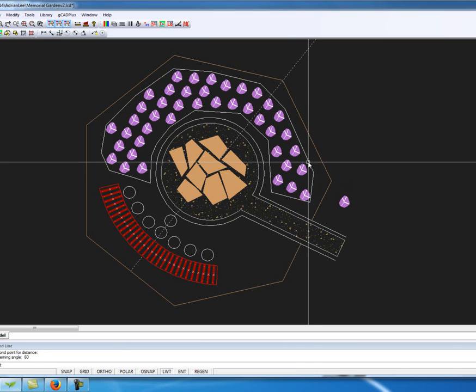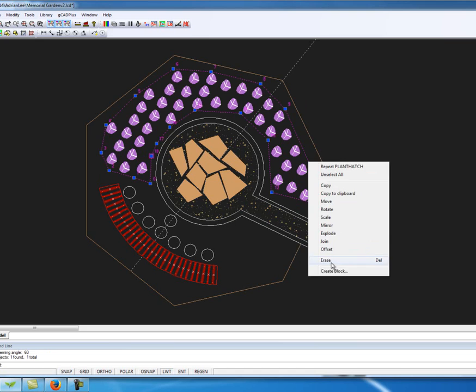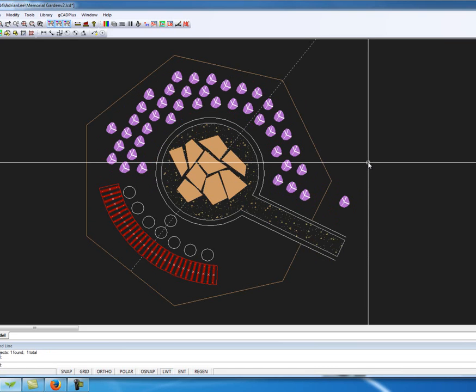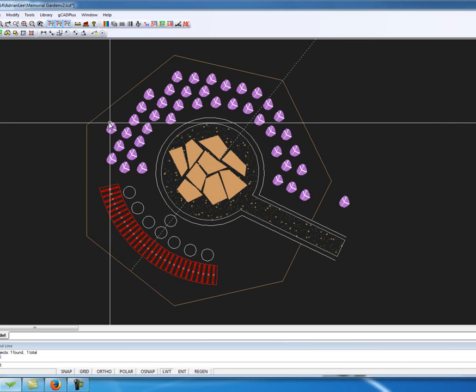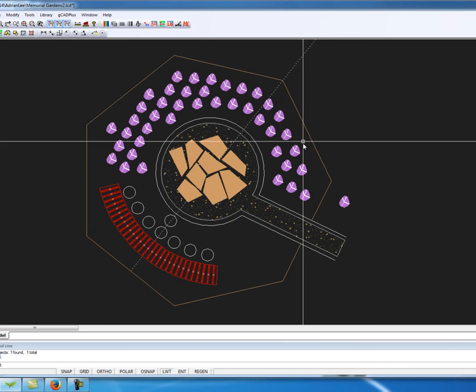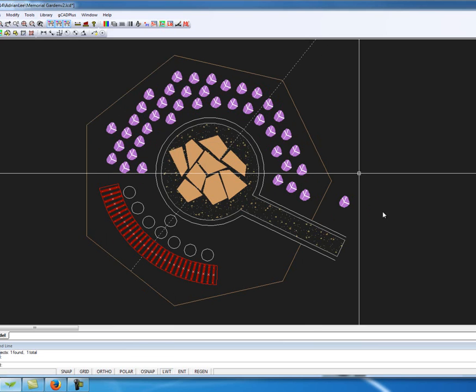And once that's done, you can, of course, delete the bounding polyline that denoted the area. So we've done some massed planting in there. Now, if I'd drawn the polyline closer to the boundaries of my rather formal shape that delineates this area, I could have had the planting going closer. But I hope you'll agree that that's a much quicker way of applying a large number of patterns.